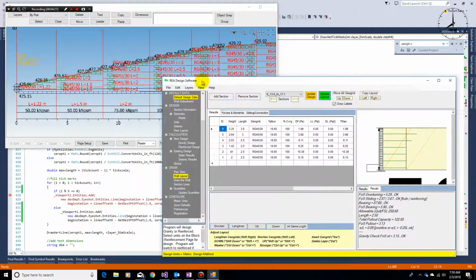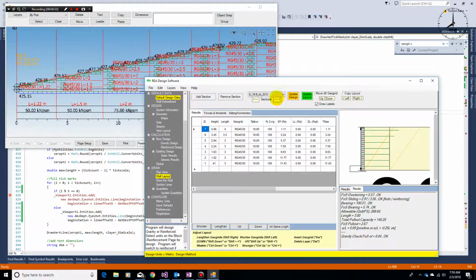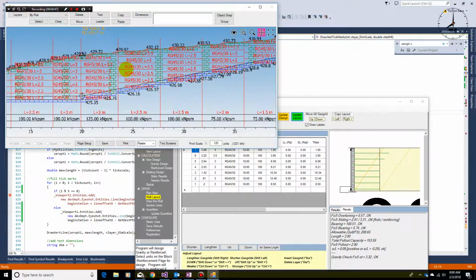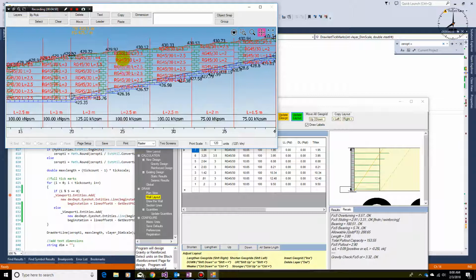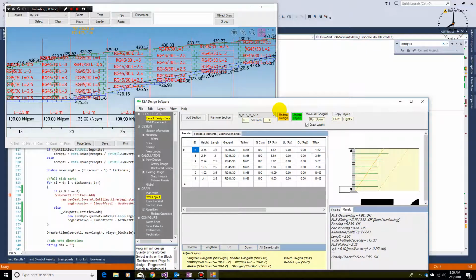Now you can see that the grids line up across. And I'll go over here to 20. We just use the tab button here. I can move those down. I'll update that view. That one looks good. Coming across here to 24, same thing. Probably move those up. And you may not want a grid right at the top block. So if you want, you can do a shift arrow down, correct that one, update the view.